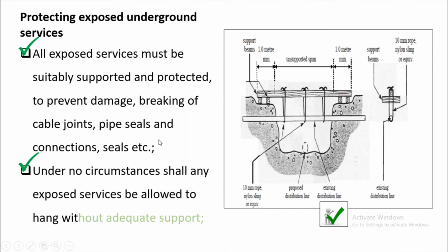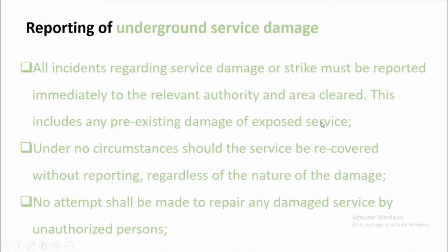Under no circumstances shall any exposed services be allowed to hang without adequate support. So, zero tolerance. If you expose underground services, make sure that there is adequate support on them.